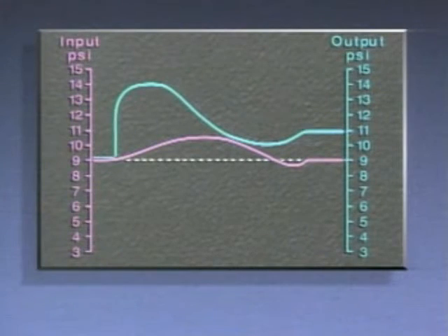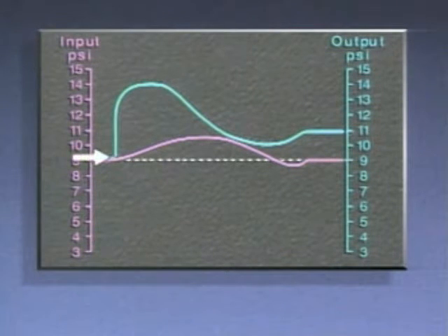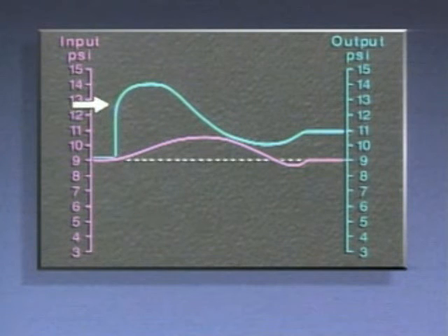We can get a better idea of how the control system responded to the change in oil temperature by looking at the controller's input and output signals on this graph. The input signal to the controller represents the oil temperature. As the graph shows, when the temperature of the oil first began to increase, the controller immediately produced a corrective output signal that reflected the rate of change. This boost of control action stopped the temperature from changing as rapidly as it would have without rate action.